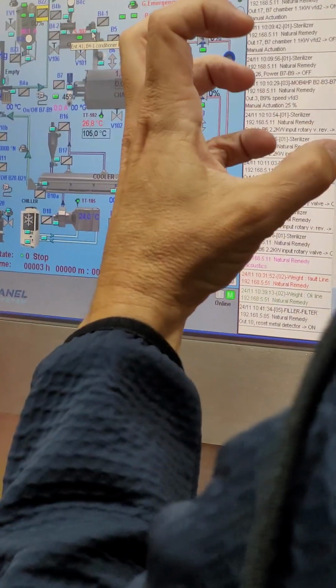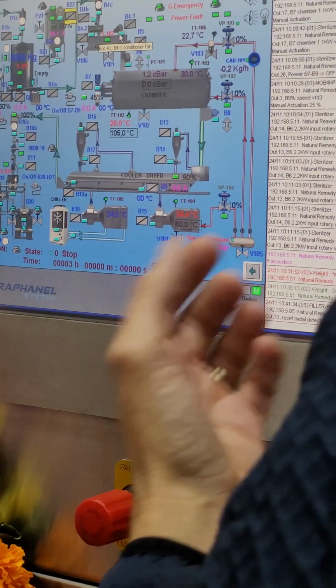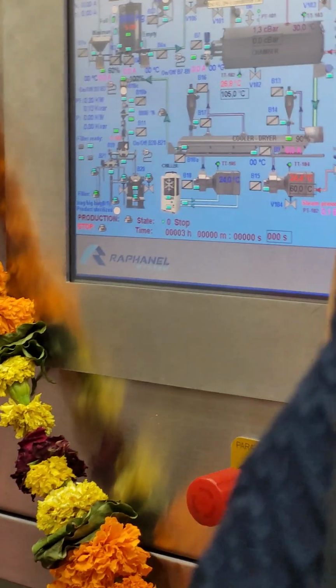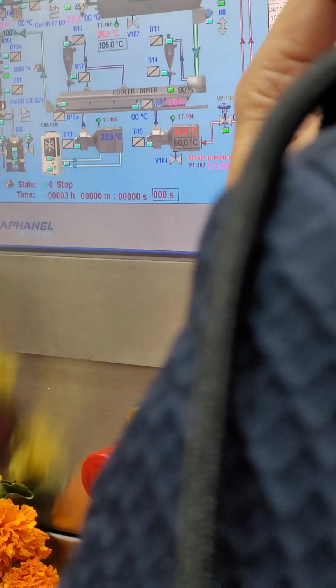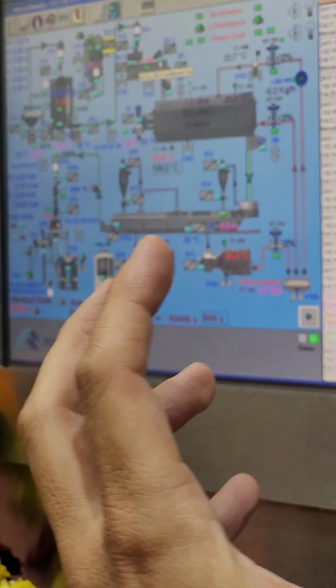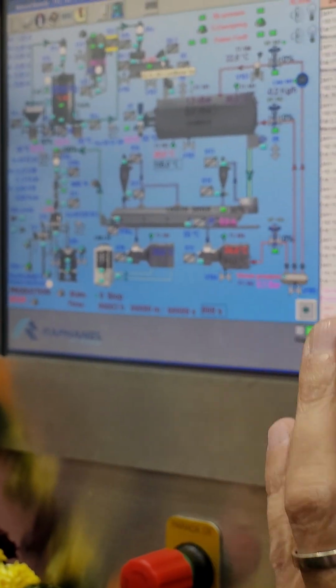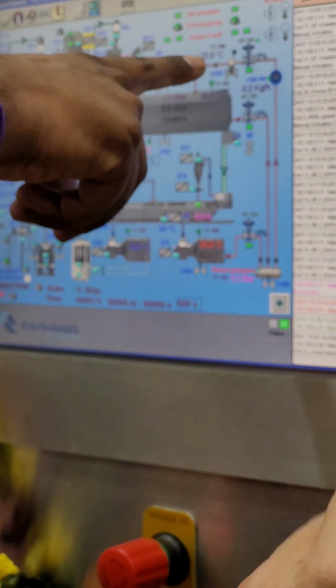The rotary valve is blocked. The motor alarms. It will not take overcurrent, but somewhere a lump is formed, the powder will not flow, bridging will happen, it will not come down. At the end, any motor is blocked. Yes. So steam injection is stopped in that condition, if the material is jammed over the rotary valve.